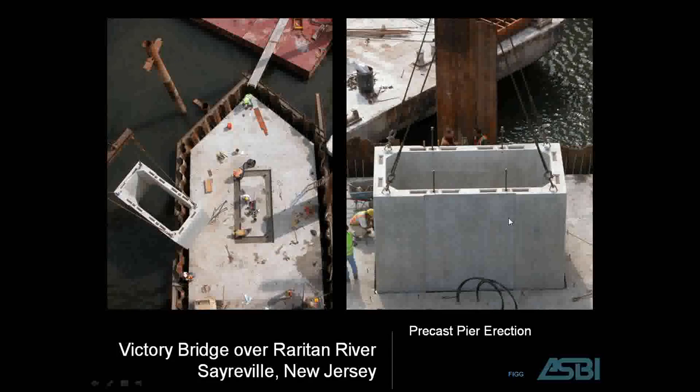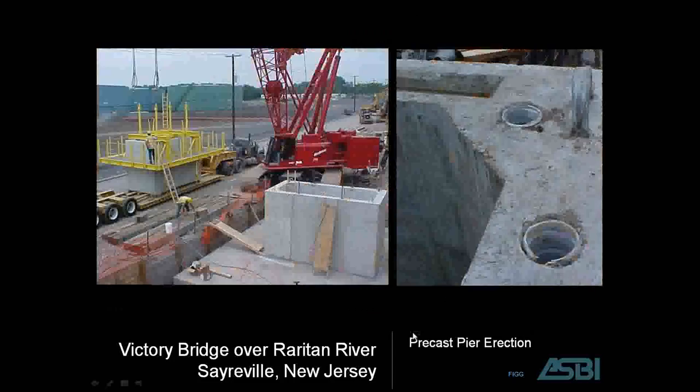Here we can see the segment being transported into place. This is the existing footing here on the left. The segment's placed down into the pocket that's been formed up. And once it's shimmed up into position, into the correct geometry, the segment's grouted into place. You can see here on the left, the starter segment has been placed and grouted in position. The photograph on the right shows some of the finishing of each segment. You can see the shear key. You can see the ducts that will facilitate the post-tensioning.